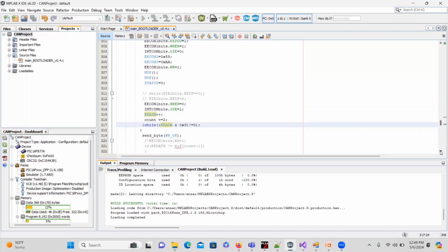In one batch, because the flash memory will do a batch flashing. So we should flash 4 bytes at one time, right? For that, we are checking whether we have reached 4 bytes by adding the LSB of the program address with 3. When you do that, you are extracting the last 2 bits. So when you extract them, you are checking whether they are equivalent to 0. If it is greater than 0, you have not achieved 4 bytes.